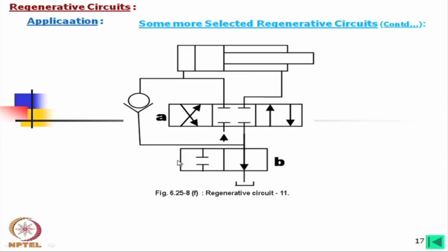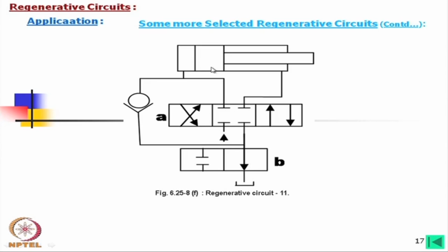But if you immediately put in these positions, this oil is connected to here, but this oil cannot go back to the tank, rather it will try to circulate, means there is no volume displacement, there is no scope, the full path is filled with oil and it is locked. So, it is a braking condition, but you should not say no operation. It has returned up to some length and then suddenly you have stopped. So, it will be in locked positions, brake positions.